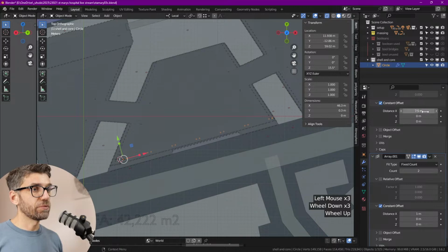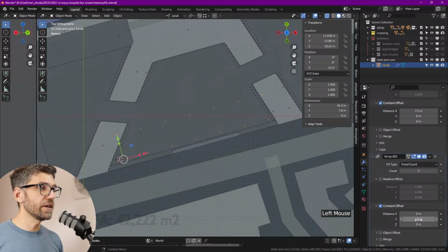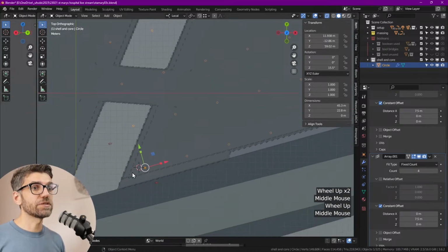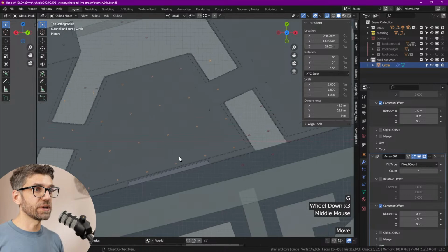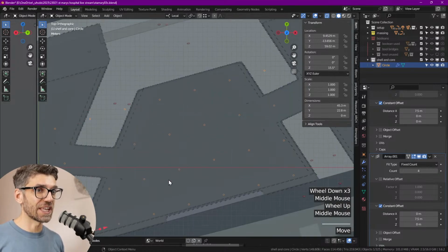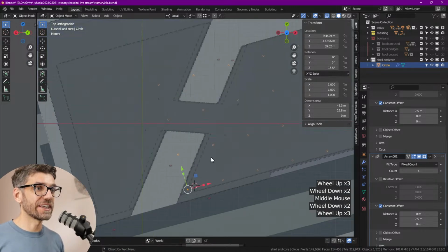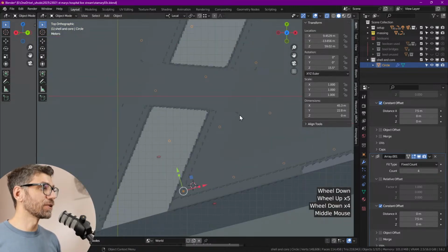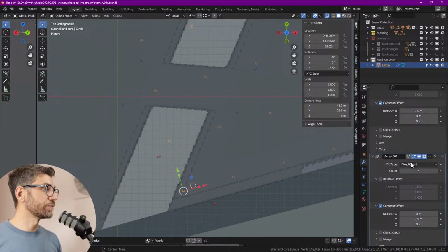So we should, well, it doesn't always need to be the same distance, by the way. Sometimes it can be different, but a good starting point would be to try to keep it the same. So let's create a grid over here. So, okay, that grid is starting to make sense, right? It's not too bad. Always we would need to create like an edge grid, a perimeter grid. But where it's going to start to get tricky for us now is with all the wonderful and interesting setbacks that we have created. Wow, in fact, even this angle here almost works, doesn't it? I guess it's almost a 45-degree angle because that's what it needs to be for this to work well. So if it's not a 45-degree angle, it won't work completely well.